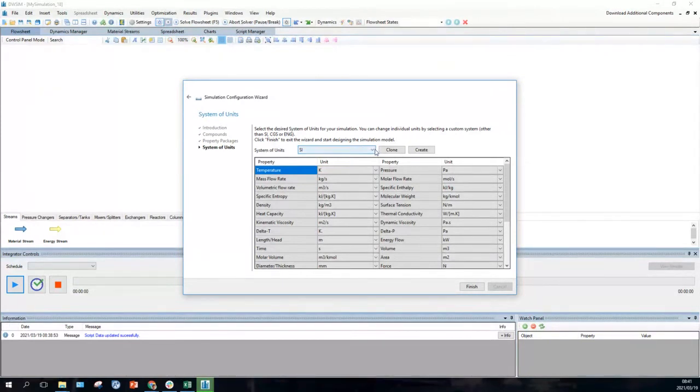They will insist that you use degree C for temperature, and for pressure you'd use kPa, not pascals. Atmospheric pressure is 100,000 pascals, so that's not a useful thing. So we want kilopascals, and C5 tends to give degree C and kilopascals. So let's choose that one, and there you can see temperature is in degree C, pressure is in bar. Okay, bar is fine.